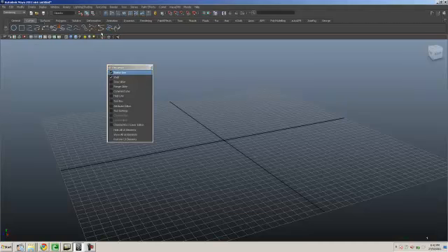If I, on the other hand, want to move it only in the Y and the X plane and don't want it to go that side in the Z axis, I would keep my finger on Control and left click on the Z axis, turning it off. I'm turning it off right now. You'd see this little square is flat, which shows you the plane that it's going to go on. It's just going to go on the X and the Y axis.